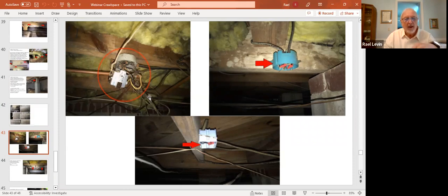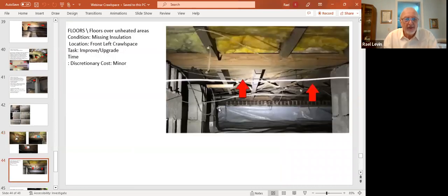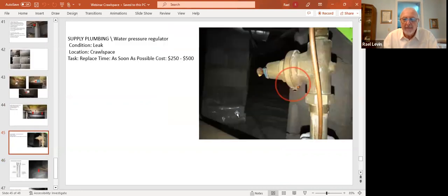If there was foam here, we wouldn't be able to see it, but we'd like to see these installed with a cap on them. They're a few bucks a piece. A lot of this gets missed, open splices, etc. We just want everything secured in there in case there's a short or a spark that perhaps could cause some damage here with ignition to insulation and becomes a fire hazard. Again, missing insulation sometimes, we're finding that, and we're just saying that's a minor fix right there.